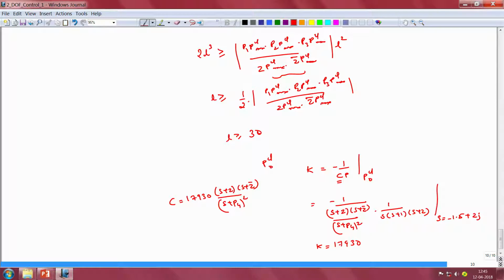We are now done with the second step of our control design. We have determined in the first step the locations of the zeros. In the second step we have determined the locations of the far away poles and used both these pieces of information to determine the overall feedback controller of our system. What is remaining is for us to determine the structure of the pre-filter.